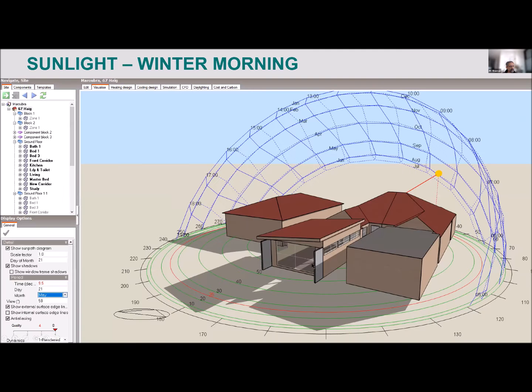Another thing you can do is the sort of solar dome analysis that Mansi was talking about using DesignBuilder. Once you've got the model built in, those are those two sun shading wing walls there, the privacy screens I was talking about. Now, remember, this is Sydney. It's in the southern hemisphere. So July is winter for us. That's why the sun is low in the sky in July here. In Delhi, in India, in June, July, the sun will be right on the top. Everything is flipped around, okay? And you can see that as you do the runs.